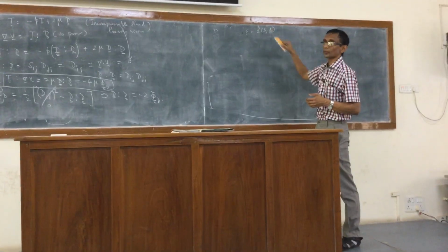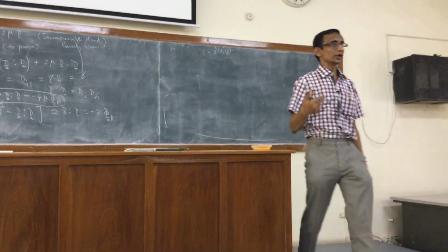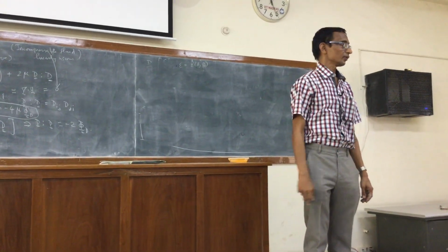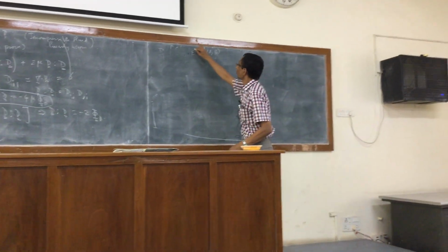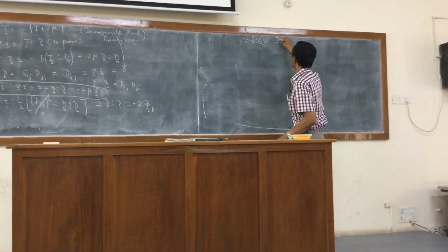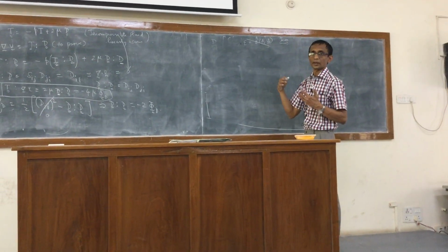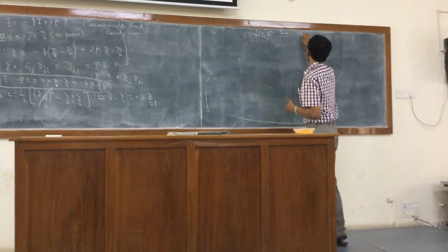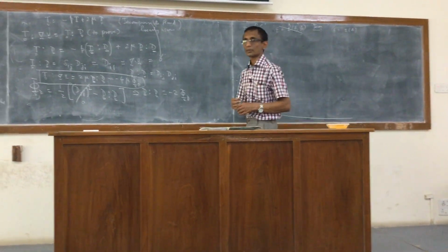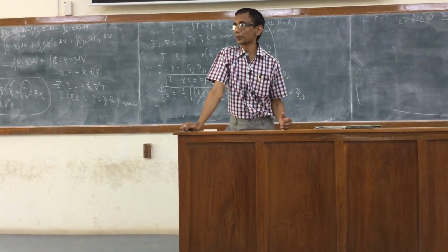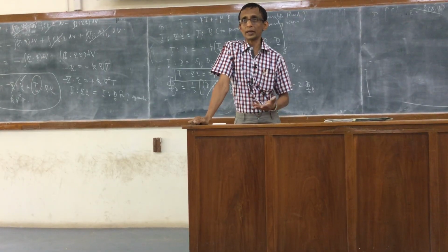But anyway, whether this is expressed per mole or per mass, for an incompressible fluid the specific volume is going to be constant. So it's not going to influence the internal energy. Internal energy will not be a function of that. So for an incompressible fluid, I will simply convert this to a relation between the per mass specific internal energy and entropy, E of S, because for an incompressible fluid the density is constant and it is not going to vary at all.